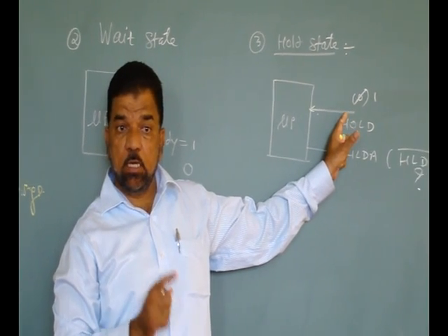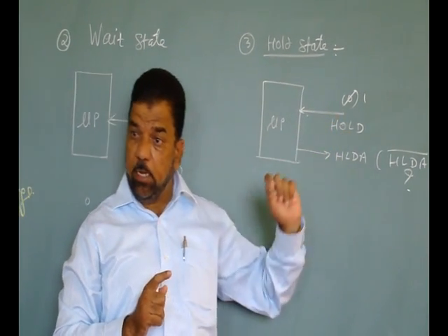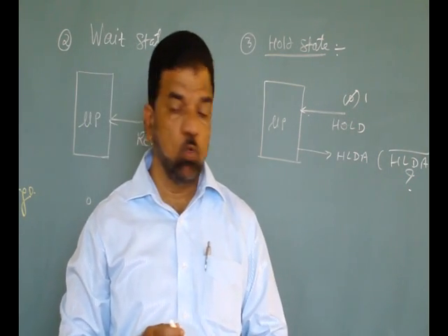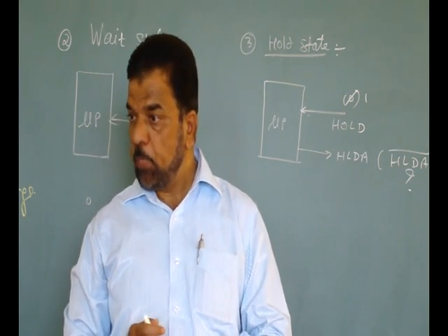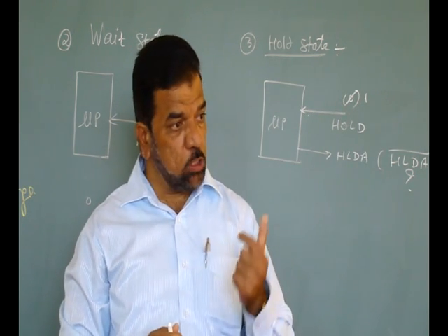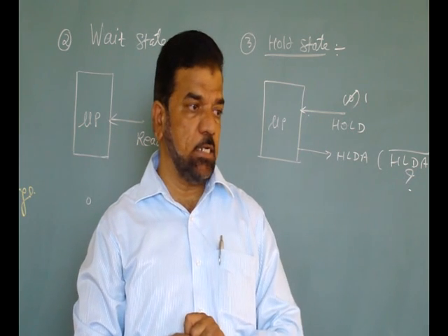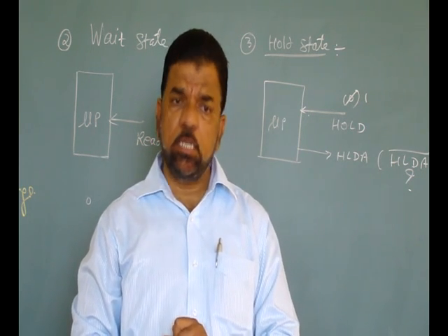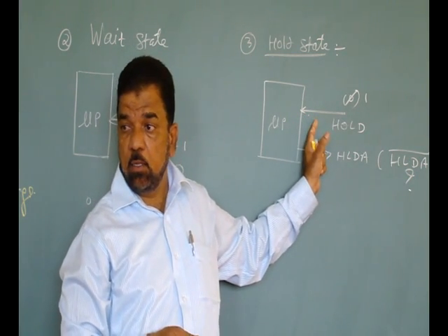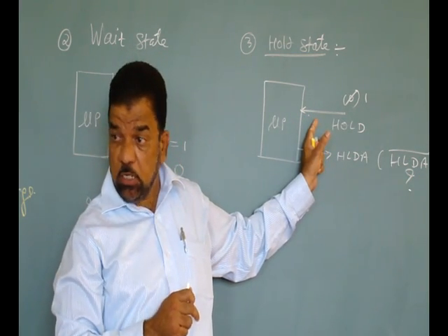If the logic here is 1, then the internal flip-flop, the HLDA hold acknowledge flip-flop, gets set. Then the processor comes to the next T state. Now the T state is T3, because the pin was checked at T2. So it will come to T3 now.